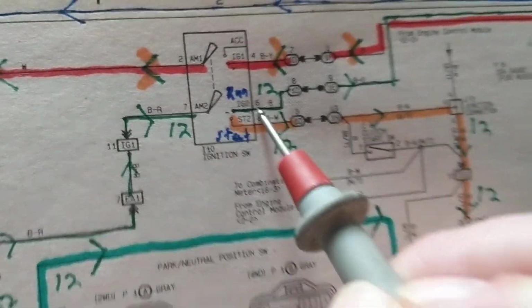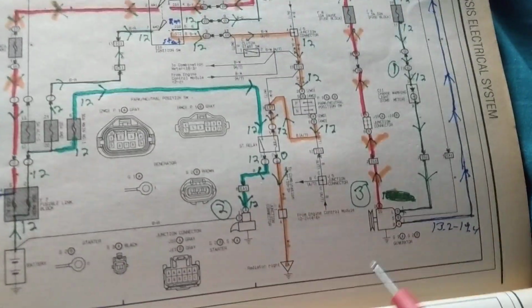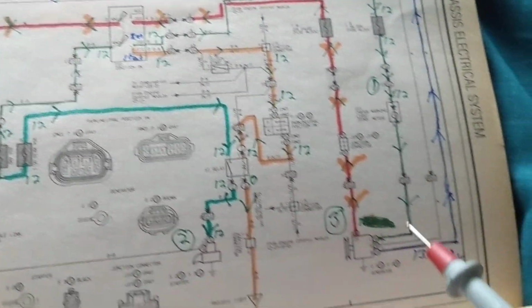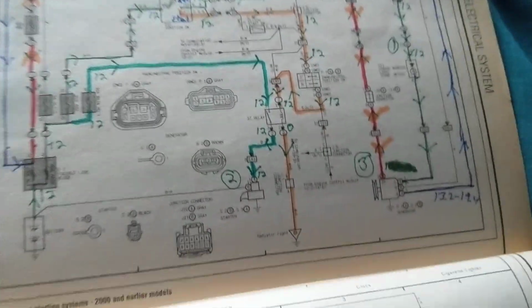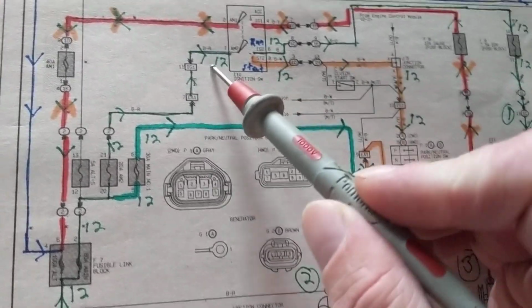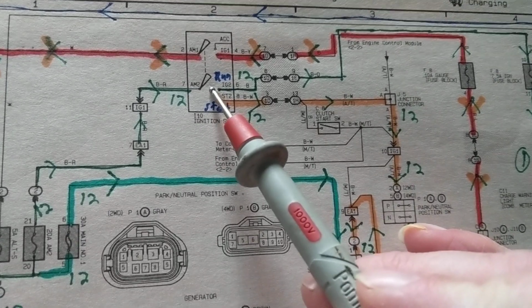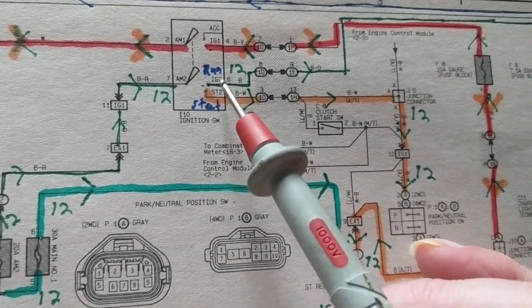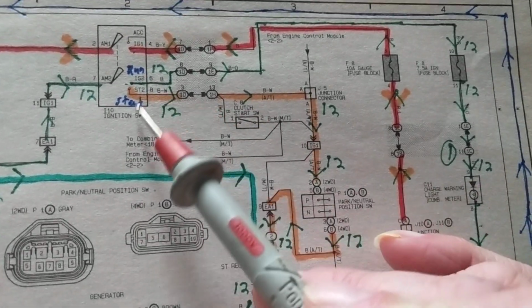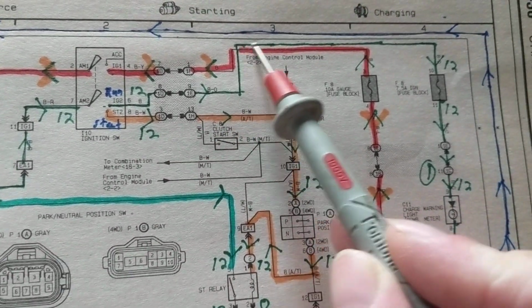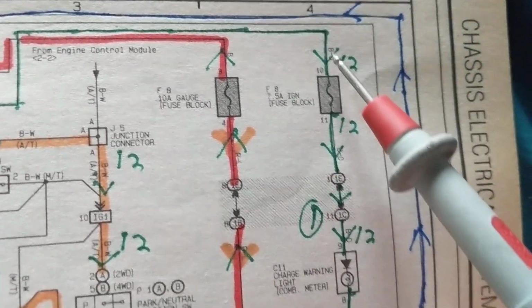Let's concentrate on that position, ignition 2. What will happen? This is tricky, but it's a challenge. But if you understand this, you have improved in your analysis and troubleshooting methods. Let's start here. Let's follow this arrow over here. We said AM2 is going to be connected to ignition 2 on the run position. Follow this line from the ignition switch. Follow this one, the thin green one, and it goes to F8, 7.5.